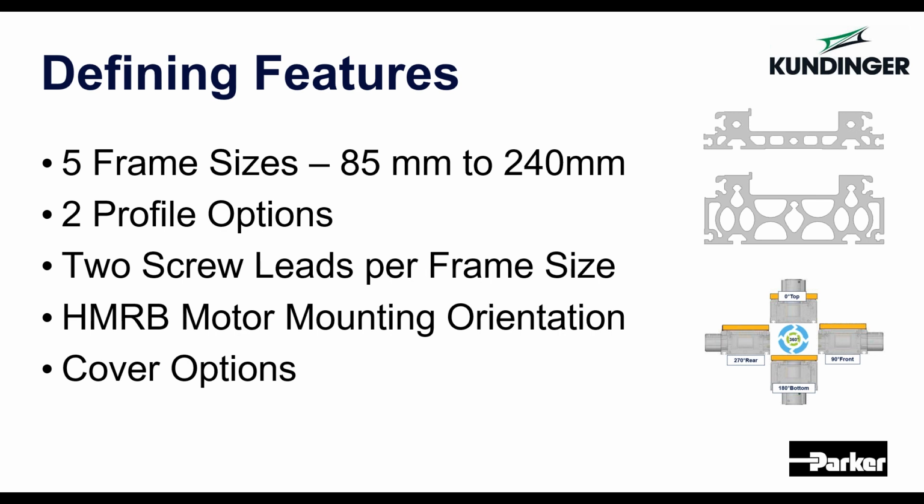We also have considerable customization capabilities, and most of what we do are simple modifications. So if you have an additional third-party motor that you'd like to utilize, we do custom motor mounts every day, custom travels, adding custom options, such as payload mounted feedback for your servo system, so a linear encoder. We put linear encoders on HMRs all the time. Those are what we would call simple modifications.